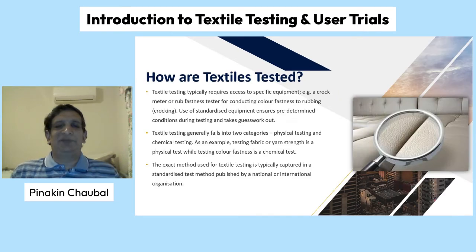How are textiles tested? Textile testing typically requires access to specific equipment. For example, a crockmeter or rough fastness tester for conducting color fastness to rubbing or crocking. Use of standardized equipment ensures predetermined conditions during testing and takes guesswork out. Textile testing generally falls into 2 categories: physical testing and chemical testing. As an example, testing fabric or yarn strength is a physical test, while testing color fastness is a chemical test. The exact method used for textile testing is typically captured in a standardized test method published by a national or international organization.